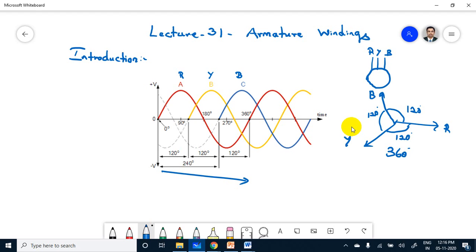Remember the statement of one cycle, call it as convolution property. Since these x of k and y of k are also periodic in DTFS, the time domain signal and the frequency domain signal both are periodic. So the convolution between two periodic signals is periodic convolution. So x of k convolution with y of k. This 180 degrees I am naming pi, and 360 degrees as 2 pi. The multiplication of two signals which are named as z of n.